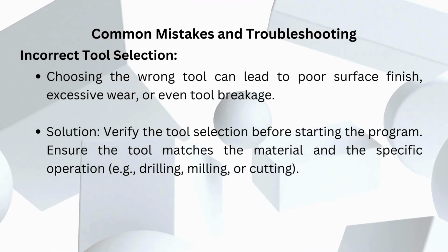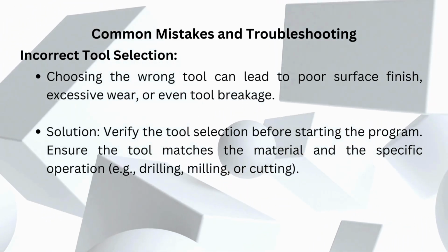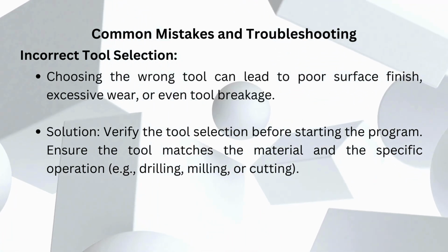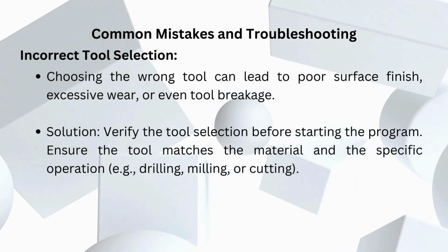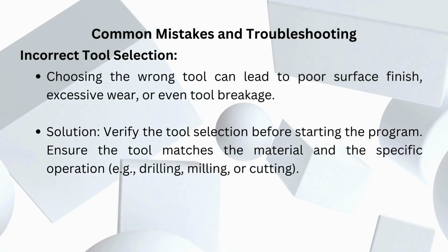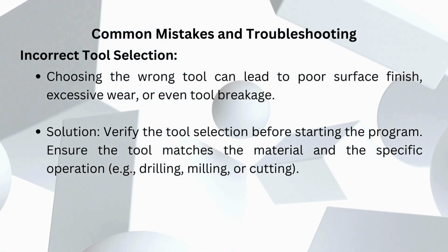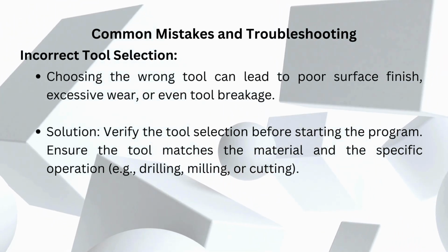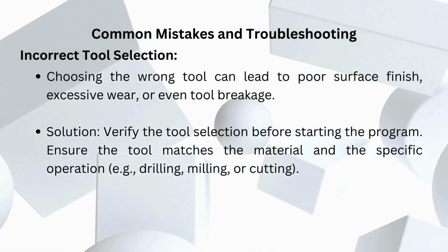Common mistakes in troubleshooting. Incorrect tool selection. Choosing the wrong tool can lead to poor surface finish, excessive wear, or even tool breakage. Solution: verify the tool selection before starting the program. Ensure the tool matches the material and the specific operation, e.g., drilling, milling, or cutting.